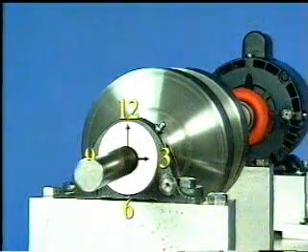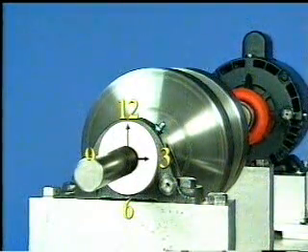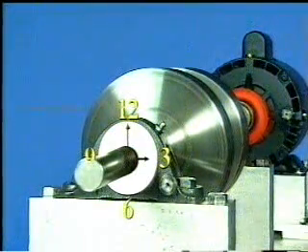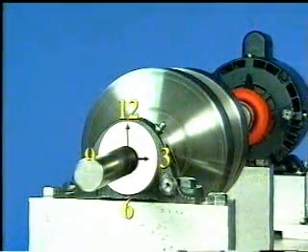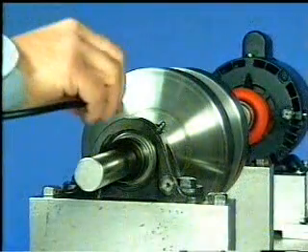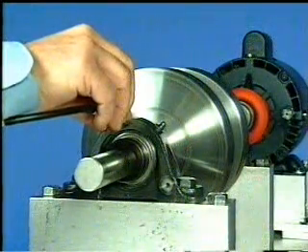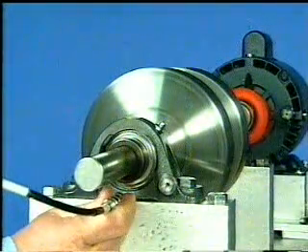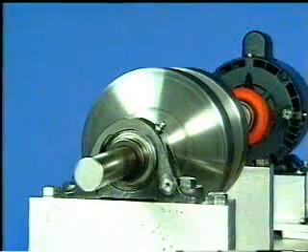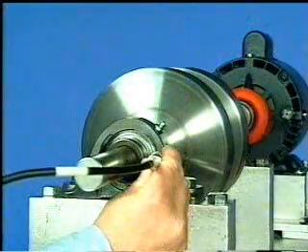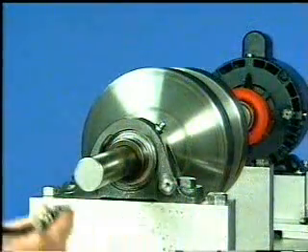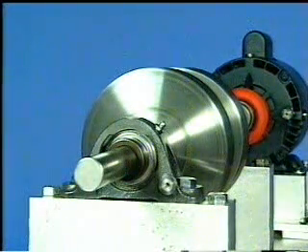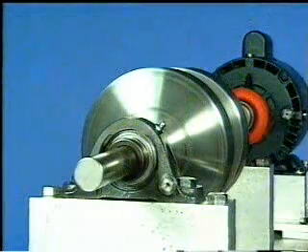Assuming a clock face over the end of the bearing or machine, the measurements should be made at 12 o'clock, 3 o'clock, 6 o'clock, and 9 o'clock positions. A cocked bearing will exhibit approximately a 180-degree difference from the 12 o'clock position to the 6 o'clock position. A 180-degree phase shift will also be present from the 3 o'clock position to the 9 o'clock position. Again, these measurements are normally within 30 degrees.